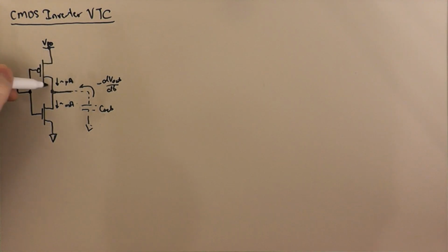That's going to put more voltage across the PMOS transistor, but it's going to be driven further into saturation. And driving it further into saturation just doesn't do very much to the current. We may get a little bit of increase due to the early effect or something like that, but it's not going to represent orders of magnitude that we need to make up the difference between picoamps and milliamps. And so